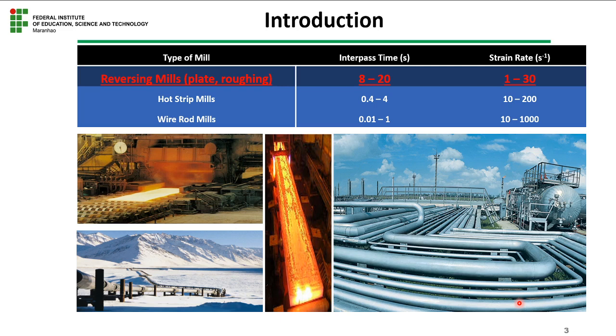The specific sites of the gas and petroleum sources require the mechanical, chemical, and technological properties to be stable over a very large range. For example, a pipeline, as you can see here in this picture, should be able to operate at temperatures between plus 50 and minus 50 centigrade or even lower.